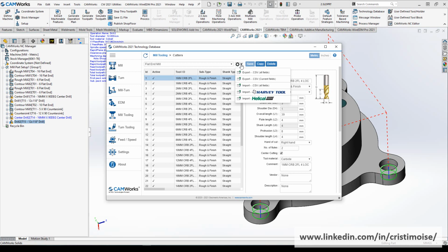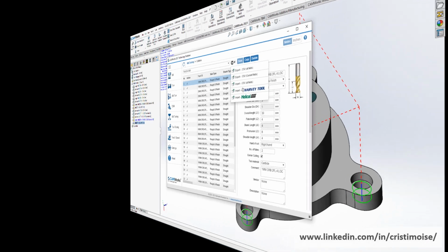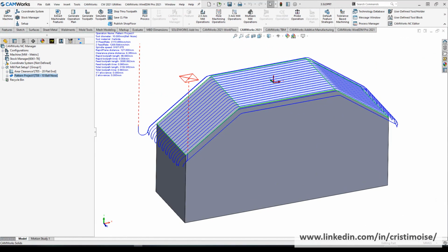The next one, let's take a look at a new option for 3-axis. For 3-axis, I told you in the beginning about the new option for the tool to roll over the surface edges, which is called Waterfall Ends. So, where it is and how we can use it. The new option, Waterfall Ends, is available for pattern project and constant step over.